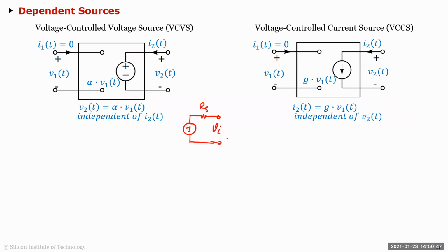And let's say I put a speaker whose impedance is usually 8 ohms or whatever it is. So that's your RL. Let's say you want to generate 1 watt of power. Let's just make it simple and make it 1 ohm. So with 1 ohm, 1 watt of power means what should the V peak be?